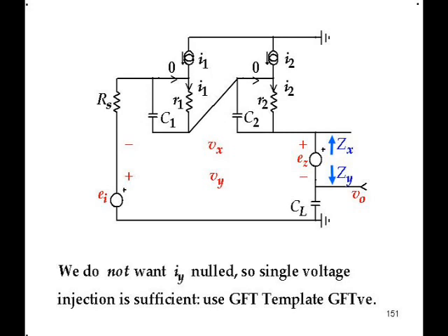If you look at zero and infinite frequency, which is what I call doing a mental frequency sweep, if you look back into Zx at zero frequency, the two caps are open. What impedance do you see looking back? You just see the R2.